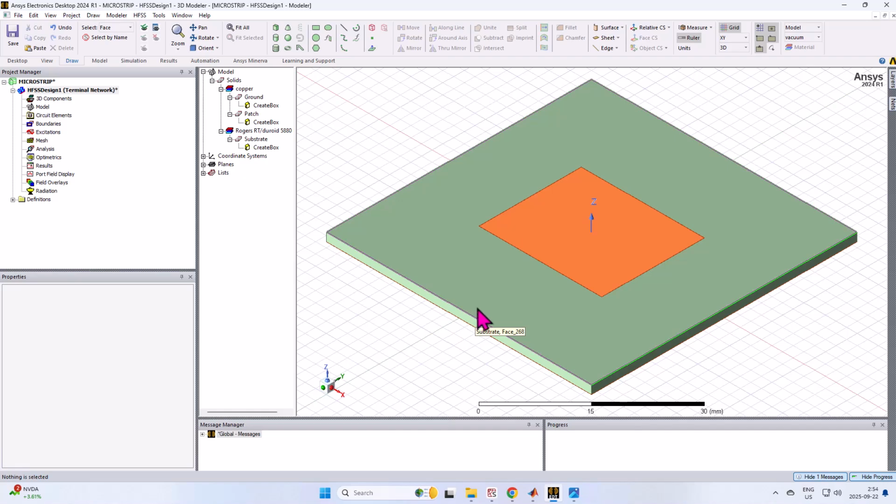So for the 50 ohms, I can do a couple of things. One of the methods, actually there are other methods, but I just wanted to explain what I'm gonna do. Normally, practically, if you wanted to have a 50 ohms input impedance for your antenna, you need to cut this here and add a trace, and then about 1/3 of this length will be close to the 50 ohm.